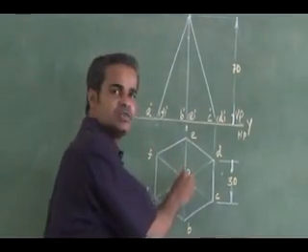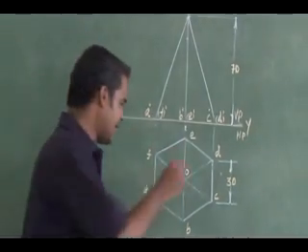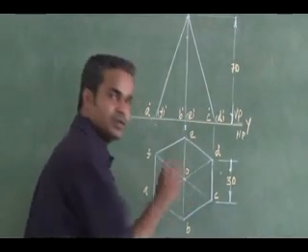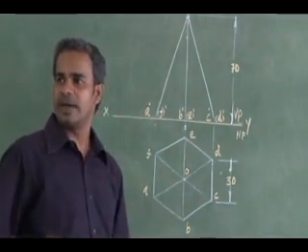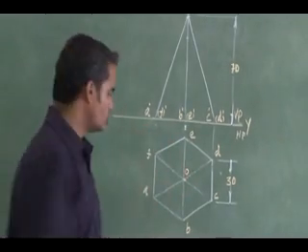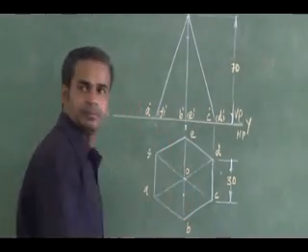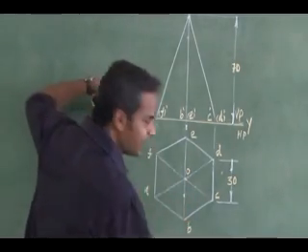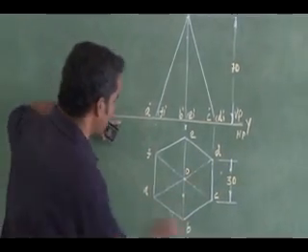In the top view, where you have the axis, that is nothing but the apex. So this is my axis, the location of the axis of the solid in the top view. From here, 10 mm away, I can mark it and I can draw a 40 degree line.